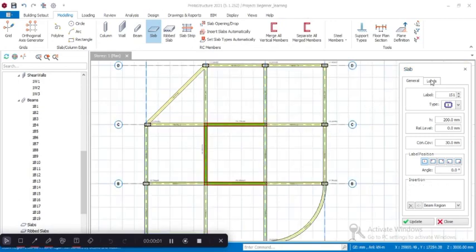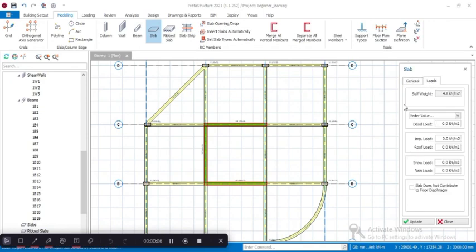So now we are going to be placing our load. So we'll go to loads. From the loads, we are looking at what we're given here. Our service dead load is 1.2, and our imposed load according to the quick start guide is 3, 3 not 30. You can add other things depending on the region, roof load, snow load, rain load, but we are not interested in all of that now. The self weight is already automatically calculated here.